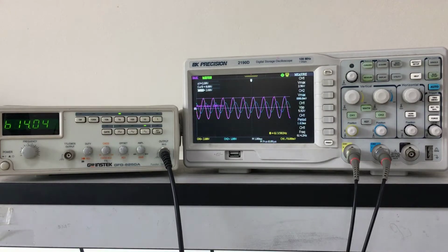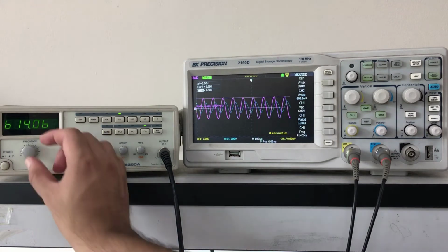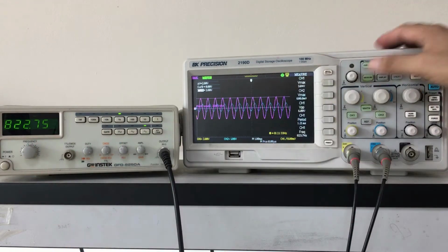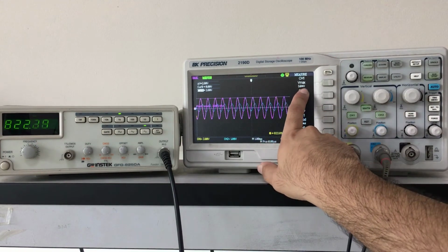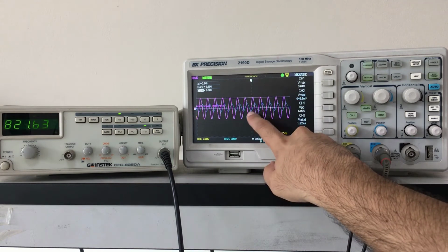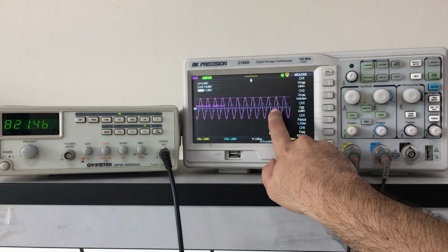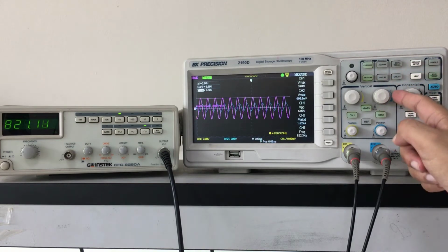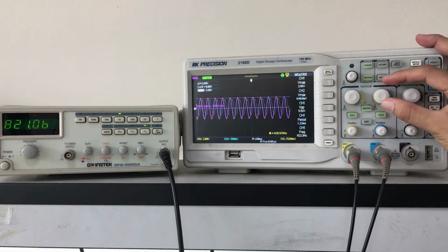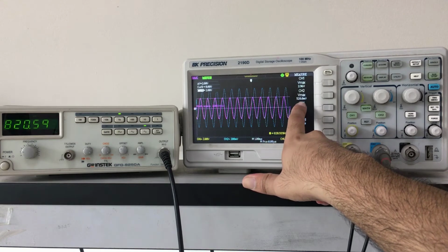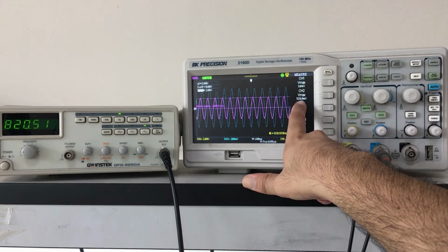Now we move on to our next frequency setting at 800 Hertz. Measure. So input is 3.04, we're good. Channel 2 Vmax is 640. We see that channel 2 is getting pretty small. To get better accuracy, we should increase the volts per division of channel 2, which we can do by rotating this knob for channel 2. We see that the voltage drop across the capacitor is 528 millivolt.